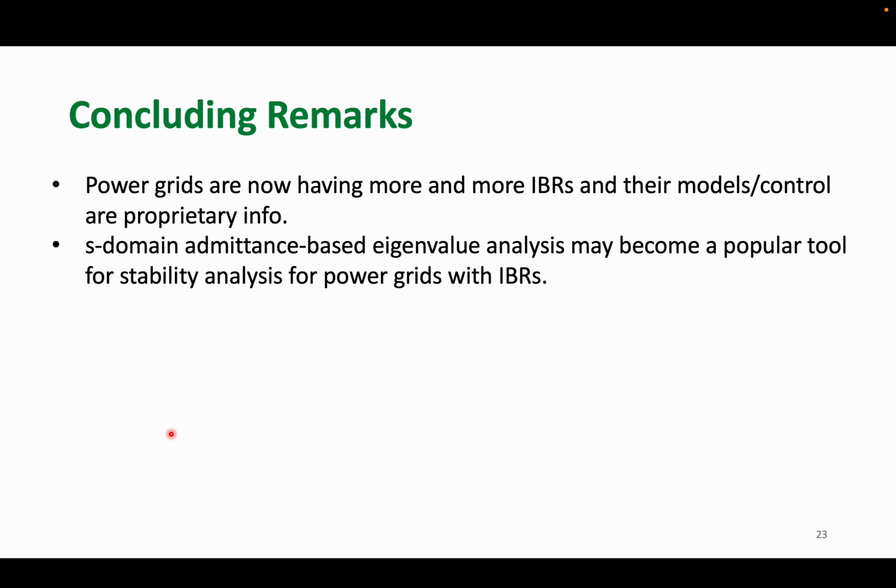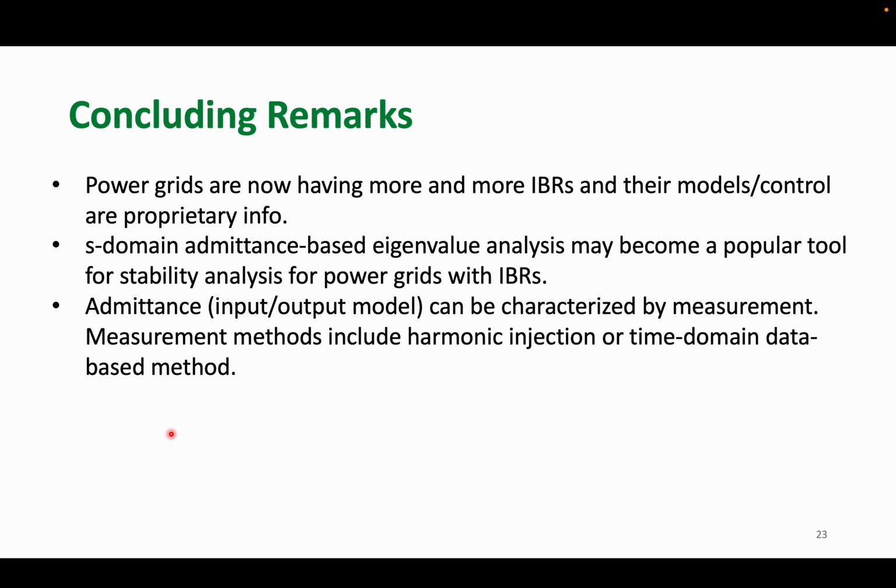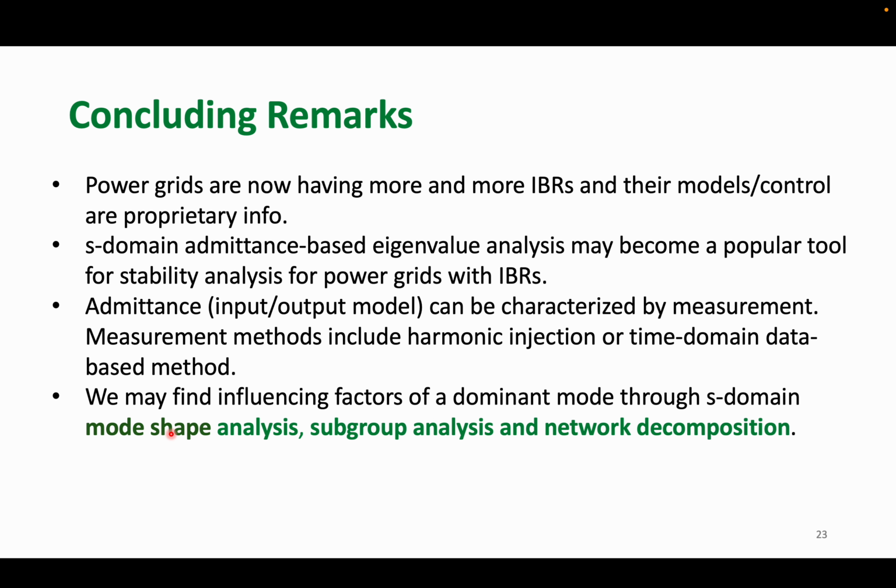This helps you integrate data-driven methods into stability analysis. It is a completely different framework because everything is voltage and current. So now you have to adopt the mentality of treating everything as admittance and use the big admittance model to find the eigenvalues.